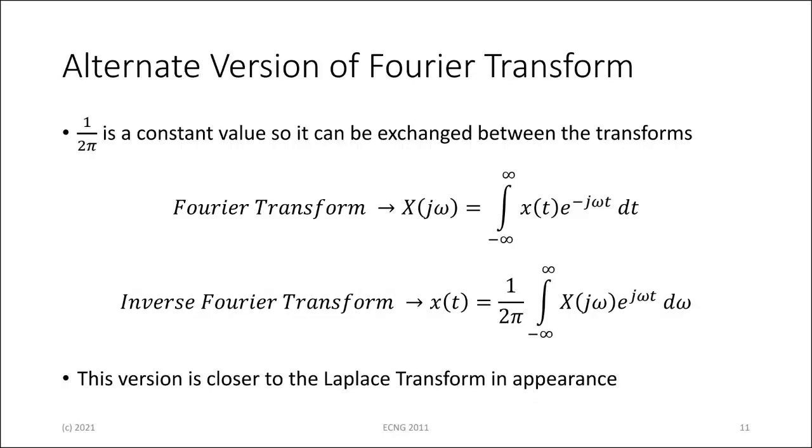Right, so where we left off yesterday, we started off by recalling that the Fourier series applies to periodic signals. If the signal was not periodic, then what the Fourier series evolved to was something called the Fourier transform. We derived it from the Fourier series by making the period bigger and bigger until it gets so large that all you really have is one cycle of whatever the signal is. We used that to derive the Fourier transform.